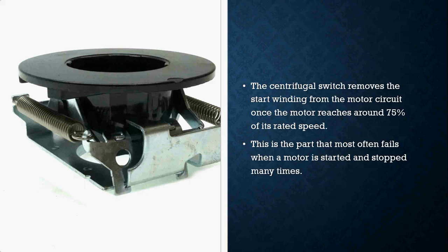And when that happens, I'm going to have my start and run winding either energized all the time, or if the switch happens to be stuck in the open position, the motor is just going to hum. It's not going to spin at all, because the run winding doesn't have enough energy to get the motor to spin.